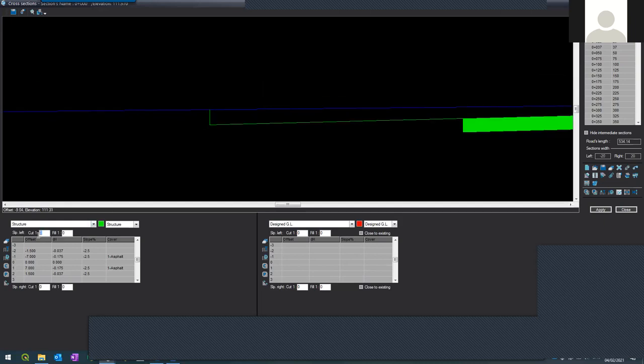How do I do it? I'm going here to the slope, and I'm telling the software, if you are in cut like this situation, go and open the cut at 1 to 2. If you are filling, since this is a template, this is not a filling situation because I'm below the ground, but if I was in filling, I want the system also to go 1 to 2.